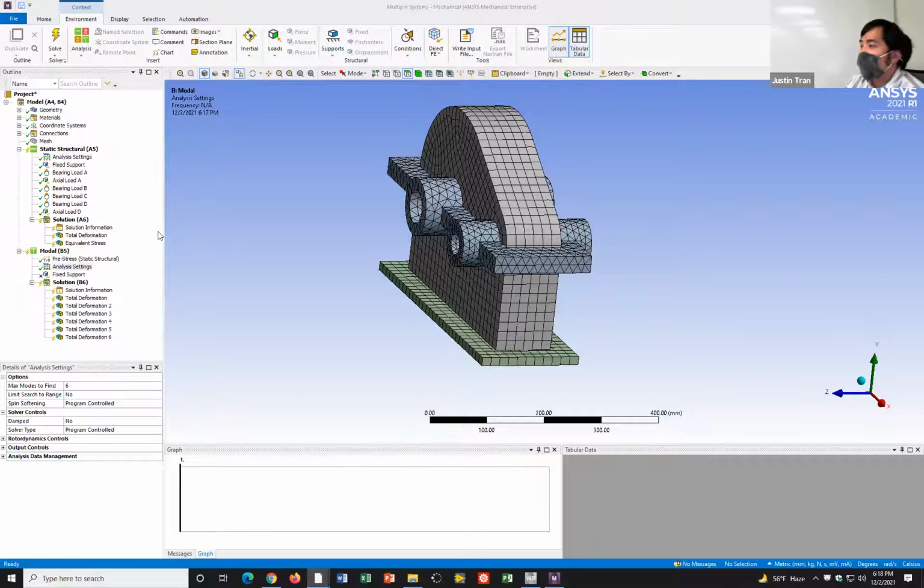Going back, if we're designing something, we always want to design the frequency of whatever we're designing to be much greater than the fundamental. There are two things. There's the frequency of the forcing, whatever vibrating component you have in your structure. In this case, since we have gears, it would be the RPM of the gears that are inside. You want that forcing frequency to usually be much less than your fundamental frequency.